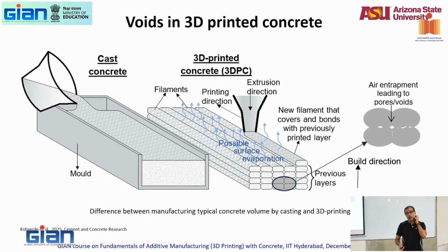Correct? Now, if I cut a piece of concrete from this one, do I really care which direction I test? No, right? Because you have poured it, it is all homogeneous and isotropic. How about this one? It's going to be extremely dependent on which direction you test. Now, what does a 30 megapascal concrete mean? Here, 30 megapascal concrete means everything that's inside here. What does a 30 megapascal concrete mean here?